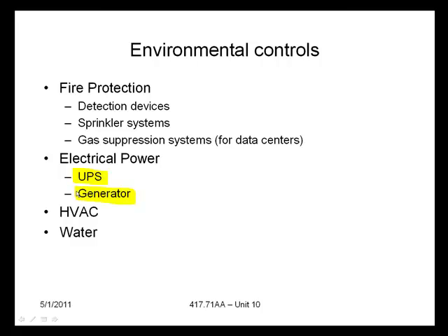You don't want to have a major catastrophic power outage and realize either your fuel has all evaporated, or it's got water condensation in it, you can't start the generator, or that the generator itself has kind of corroded out and doesn't work.